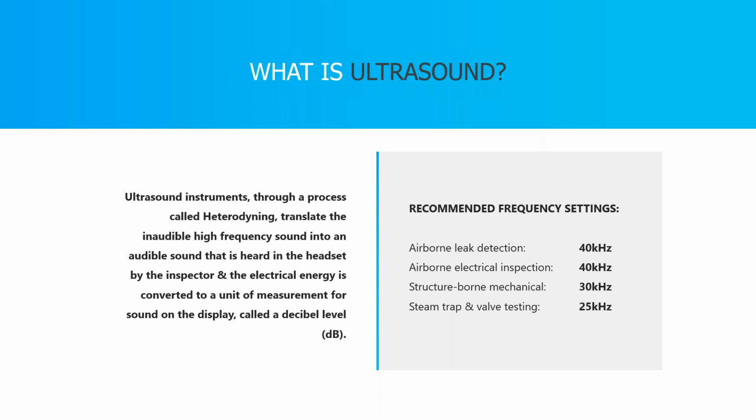And again, just for reference, if you're looking for a source of reference for these frequency settings, there is a recommended standard for ultrasound. It's an ISO standard. It's ISO 29821. So these are globally recognized frequency settings for the different applications. But again, that ISO standard is a standard for recommended use and guidelines for ultrasound. So just for reference, if you're looking to start a program, if you're looking for a set of globally recognized standards and guidelines, then that would be a great place to start.